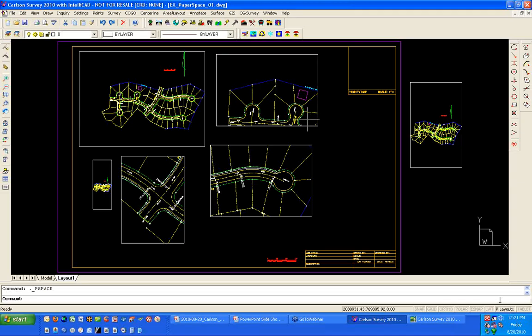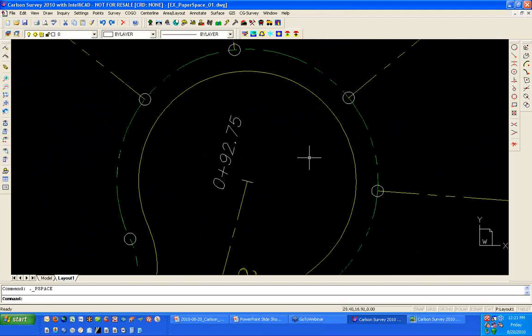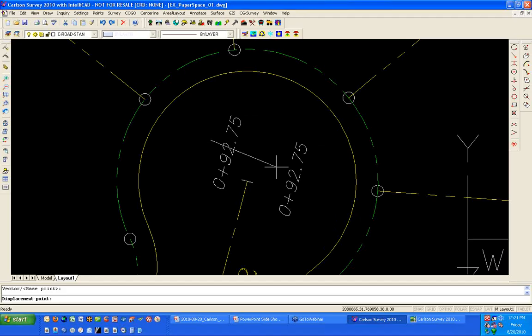And that's important, especially the 2 other toggles that I've just shown you, because it actually happens quite often. You may be zoomed in really close and double click inside so you can see the hint that I'm in model space. But I may need to make a change to something, and I've just made that change in model space.